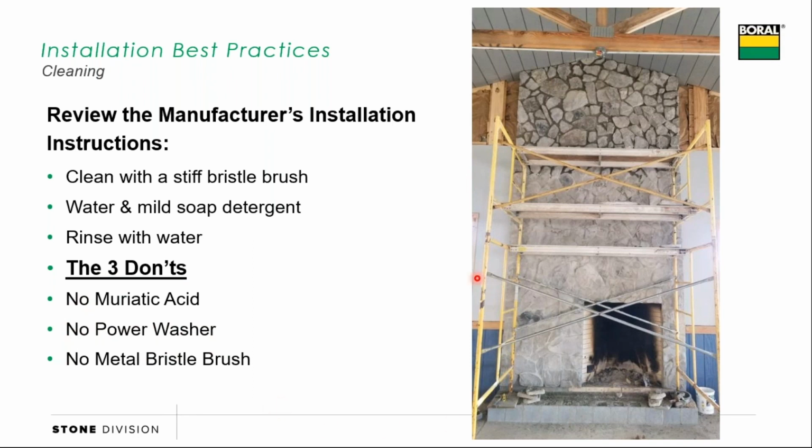I included a picture in here. This here at the top, I should first start by saying this entire fireplace has stone installed on it. This is what the stone looked like. This is what it looked like after somebody decided to use acid to try to clean the stone. The stone is still there, but it took all the color out of it completely. So please, no acids when you're trying to clean the stone.